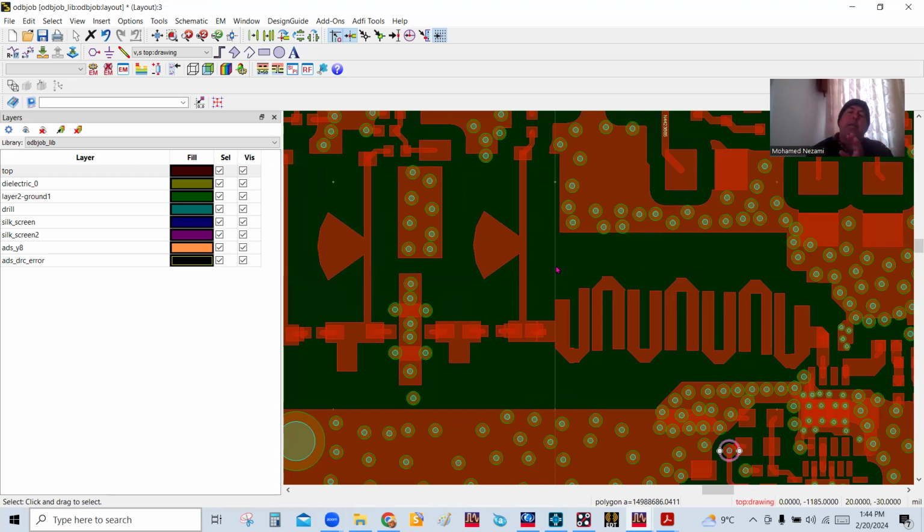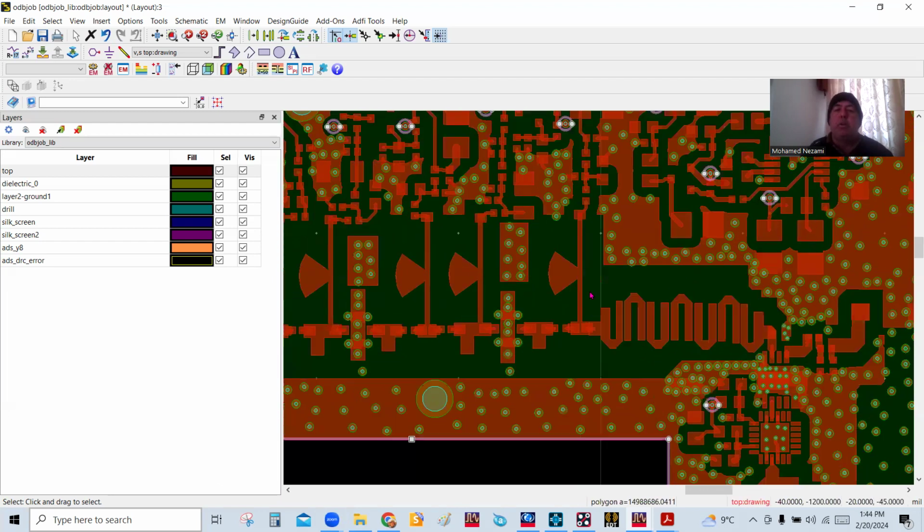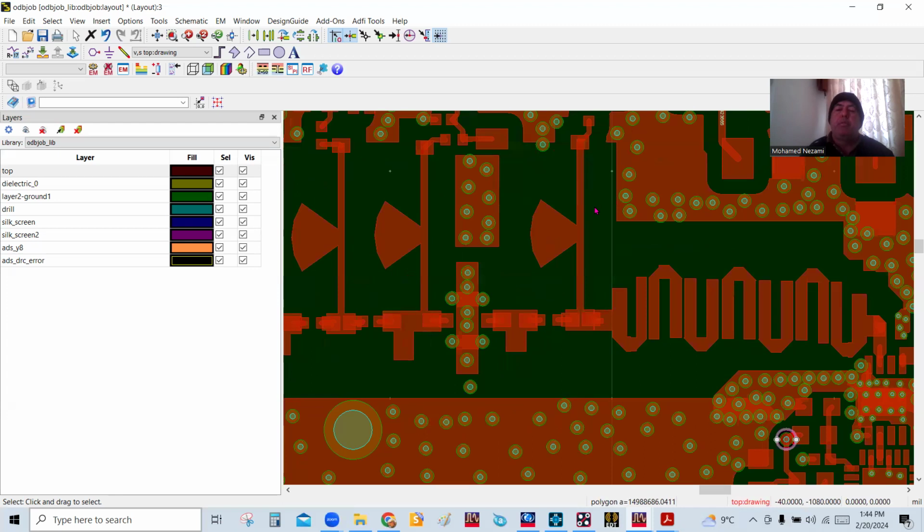Now, in next videos, hopefully I'll get to cover co-simulations, meaning you could actually chop parts of this design and do simulations where you involve both the EM model of the copper and the S parameter model or the large signal model. But right now, let's just stick to the fact that we're trying to verify that this board is okay, that all the designs that came in from different members of the team have been designed correctly, because you might get this filter from one designer and the LNA from another designer.